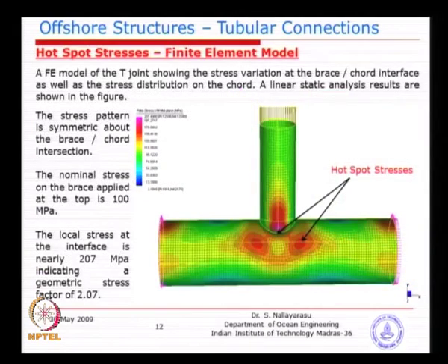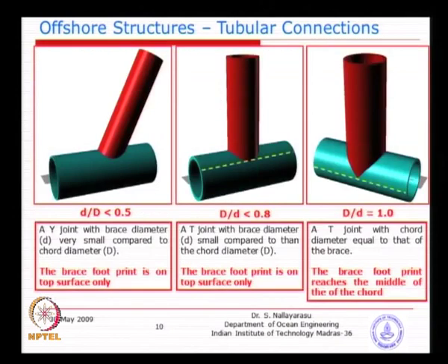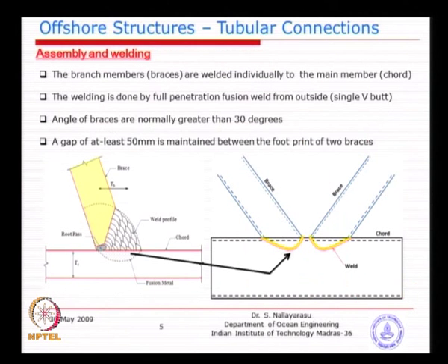I think you might be seeing here that the change in stress at that location could be substantially larger, and that is the reason why we need to know. So, we will come back to this picture later. Basically, the reason why we need to know how it is welded is to understand the distribution of stresses at the location of the welding, and that makes the difference, because that stress is larger than the stresses applied elsewhere on the plate.